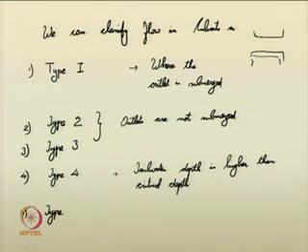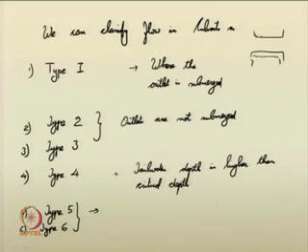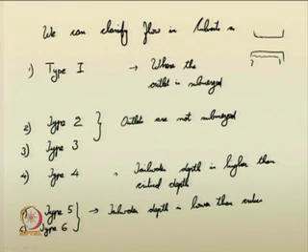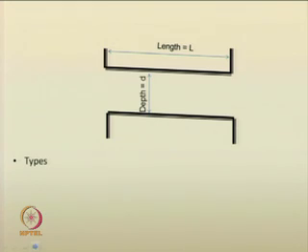You can have type 5 flows, also type 6. I can mention both together here. So, there are basically 6 types of flows in culverts. Type 5 and type 6 are where the tailwater depth is lower than critical depth. So, these conditions I can now suggest again.